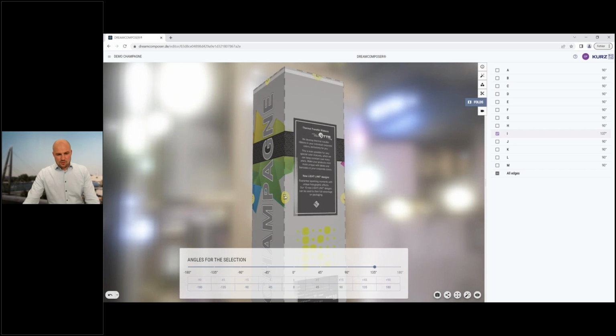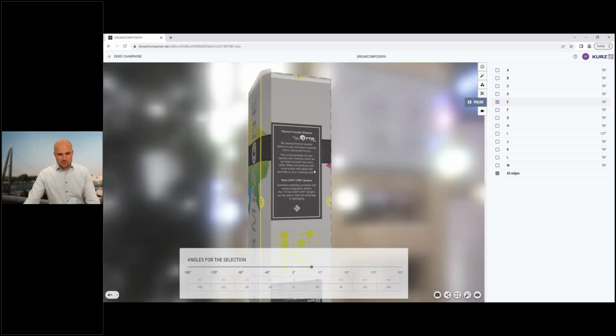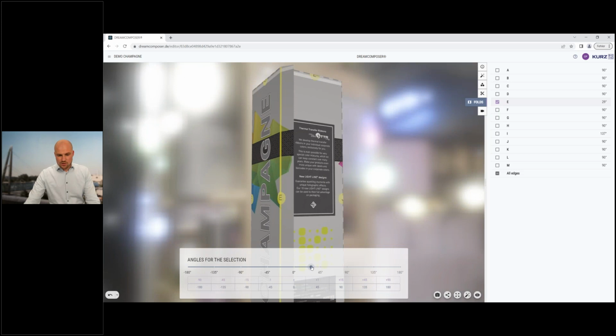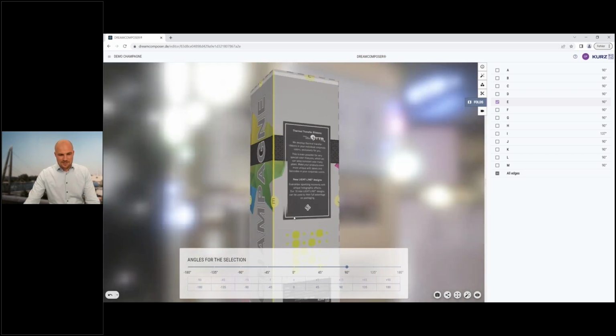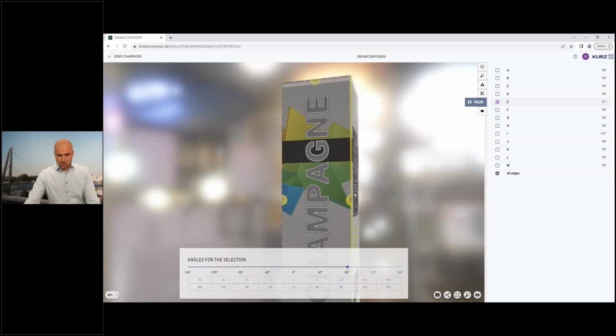What we can do here is just select that, and I can fold that a little bit outward so we see this lash, how that comes out. But to get rid of this, we just fold that inwards so we have that 90 degrees here, so you can see how that flickers. And we just fold it inwards by 1 degree, for example, and then this flickering goes away.